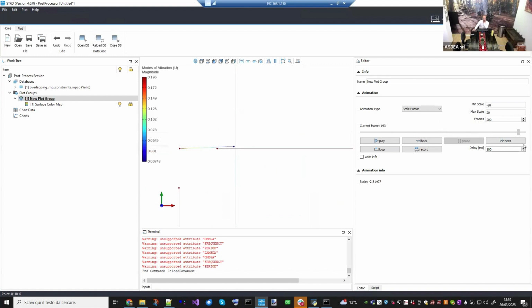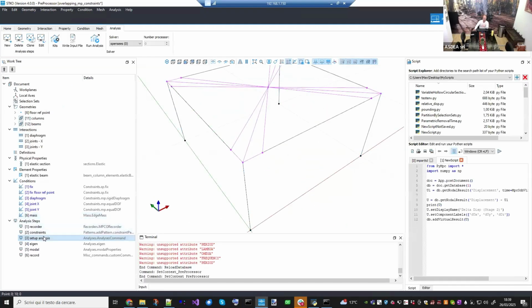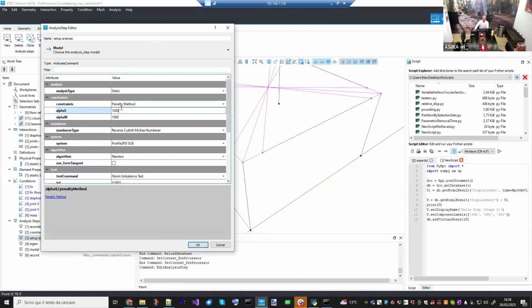Okay, because now the penalty stiffness that is down here, imagine the penalty is like placing very high stiffnesses on the degrees of freedom which are constrained. But now I use a very small number, so this stiffness is not really stiff. So it displaces together with the structure, okay? And if I make it even smaller, you will see that it displaces even more. So let's exaggerate here.